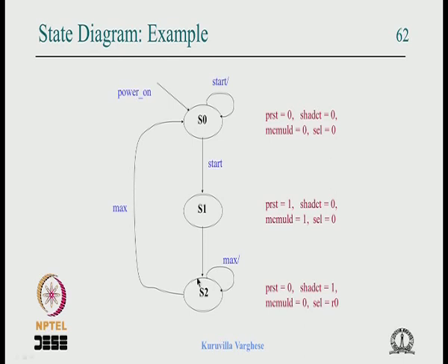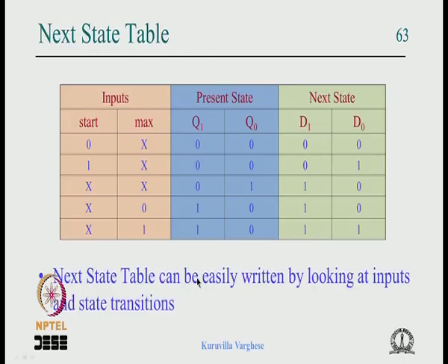So let us look now at the output logic, and as I said, it is not good to write the outputs here. Some textbooks will show you the various outputs and say what the outputs are for 00, but that is very crazy, because this being a next state logic table, 00 is repeated twice. So you are forced to write the output repeated twice, and we have no way to know whether the output is a function of the present state only or of the input, and there is confusion.